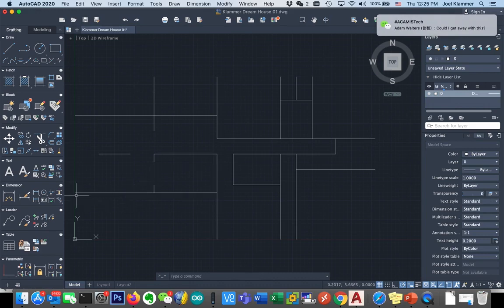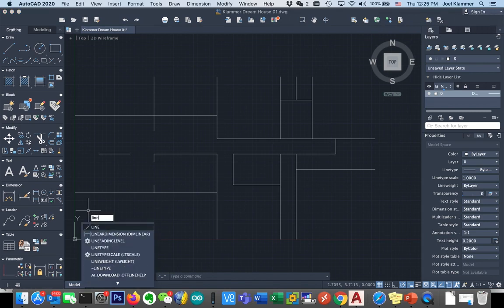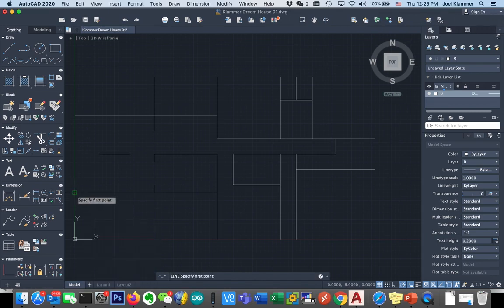So what I'm going to do here is put them back in again. Using the line command, Line, enter. I'm going to click on this first point, not using an offset this time, and then click on this one. And as long as you get these points, they're not bad. But now I need to do the patio, and there's no point out here to click on. So what I can do is simply type in 5 meters, because that's how deep it was. That'll take me to that point, and then I can go over here and click that point. I'm going to hit enter at this point, because that finishes that side.